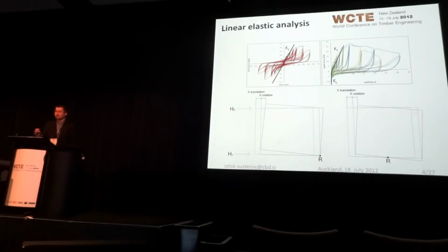However, if we're dealing with torsion, or we're dealing with higher vibration modes, so for higher buildings, displacement-based design has to be also corrected with correction factors that come from the modal response analysis. So let's not underestimate the power or the influence of the modal response analysis, which is actually not as simple as it may seem at first glance for cross-lam.